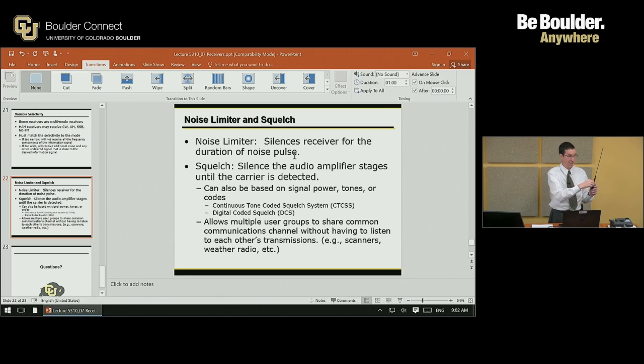So now if I turn the squelch way up, and a weak signal comes along, I might not hear it at all. So I want to get right on that hairy edge. That allows the weak signals to come in and turns this on, and I can hear it.